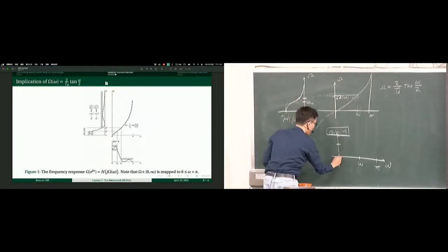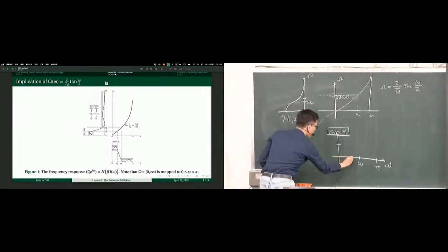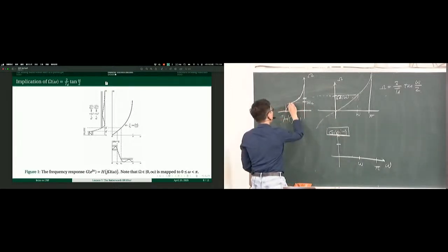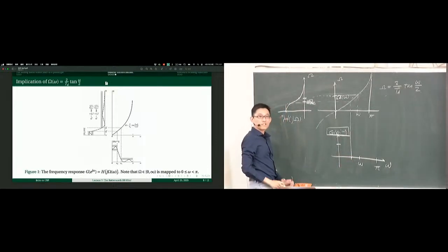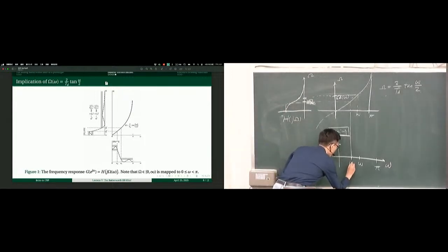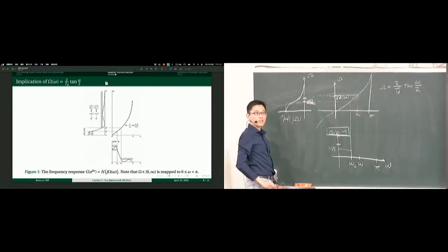So it's DC, and the gain is 1. Okay? Corner frequency, and then it goes both ways, actually. Big omega C, corner frequency right here, corner frequency right here. So you can go freely between big omega and small omega. Okay? So corner frequency right here, small omega C. We know that right here the gain should become 1 divided by square root of 2, and so on.